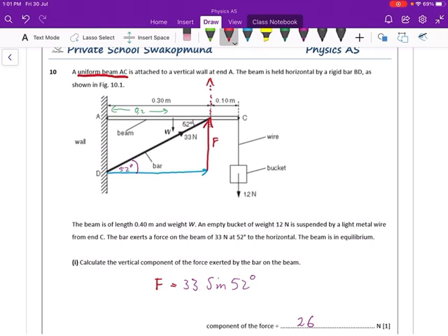And remember, what's my definition? It's perpendicular. We're working perpendicular, so we can't work with a force at an angle. We can only work with perpendicular. So the horizontal component of that bar is not going to contribute to the moment. It's only the red force that will contribute to the moment. So we have two forces working clockwise. That is going to be my 12 Newton this way, and my weight, that's going to take it clockwise, and then my red one taking it anti-clockwise.